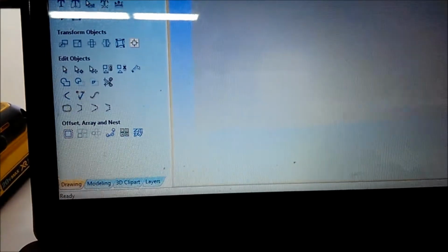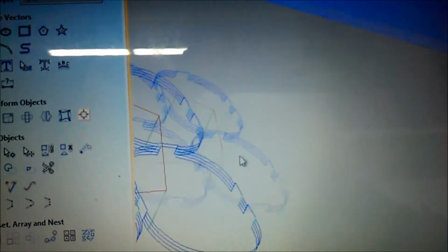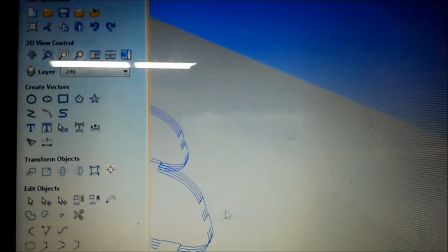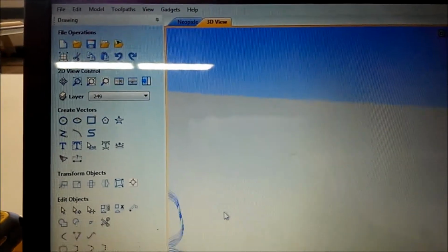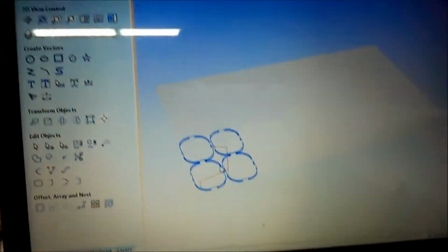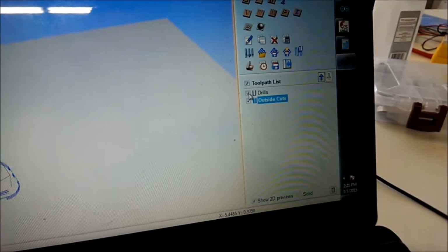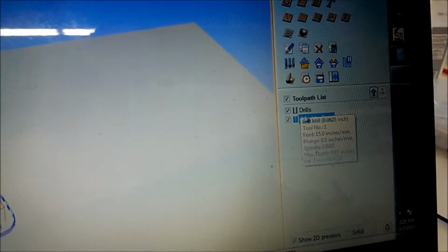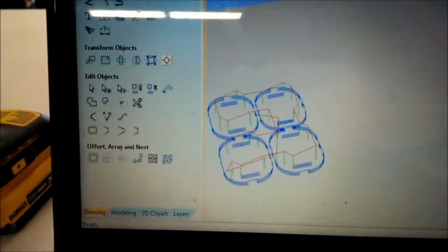If we go and look at what the toolpath looks like on that, you'll see that for the outline we have multiple passes it's going to take. So it's going to take some pretty shallow cuts, and then I also have these little keys here which should keep them stabilized as they're getting cut out. We can do a preview of this, and actually I'm going to do a preview of both of these. So I want it to do all my drills, the interior cuts first, and then finally do the outside cuts. So that's why I have the 2 toolpaths.